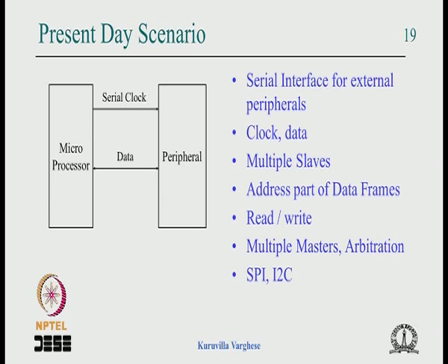So what we have seen now, in the beginning part, was basically the IO structure which can be used as output, input, IO. It can be used for cascading, and when you cascade, the tool tries to do a 2-pass cascading rather than chaining, which would incur a lot of delays, and you can even form a feedback. And we have seen some earlier simple PLDs like 16L8, 16R4, 16R8 and 22V10, which is available now. Atmel makes it, and these devices are not much used because SoCs have built-in peripherals, memory and built-in chip select decoding.